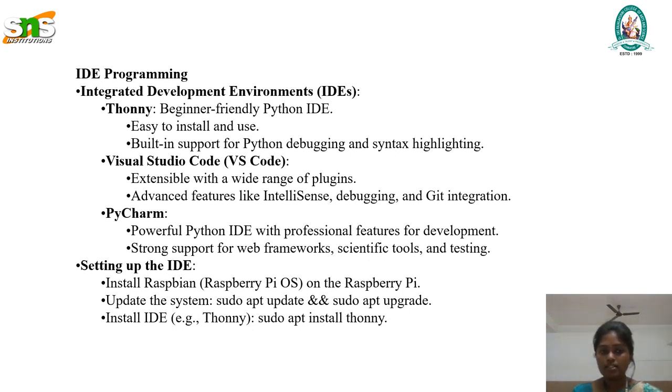scientific tools and testing. Setting up the IDE: install Raspbian on the Raspberry Pi, update the system with sudo apt update and upgrade, then install the IDE with sudo apt install Thonny.